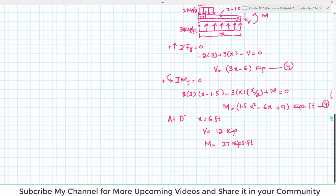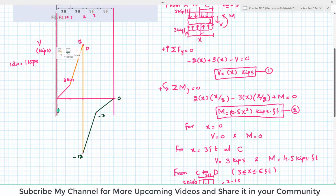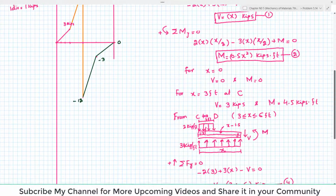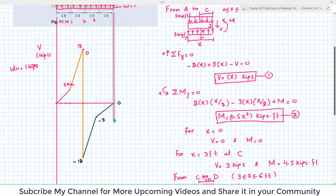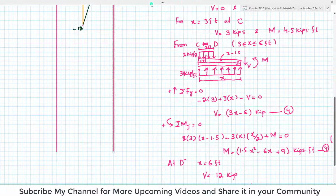So this is your shear force diagram. Now we will move toward the bending moment diagram. So for bending moment, again what I have to do is extend it below. Similarly, I have to extend the legs and we will draw a horizontal line. So here we will draw the moment, that will be in kips into feet. So let one division, vertical, be equal to 2 kips into feet.